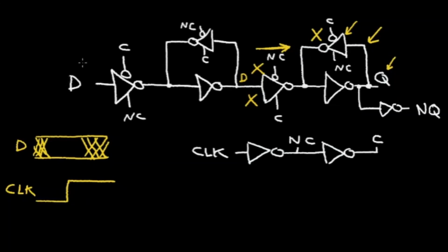And the D input to the D-Flip Flop is here. The Q output is here. The not Q is the Q output inverted through an inverter. And my clock signal is here, and the NC signal is connected by name.